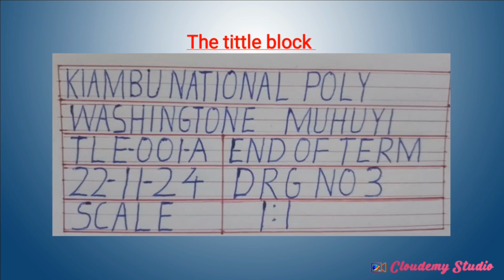So after understanding the types of lines, now we'll move to the next part, which is the title block. I'll really emphasize the title block since I told you that the marking will be done as a block. So at least an examiner has to see that you underwent a class of engineering drawing and you are taught how to design a good title block. So for this, I've just designed a sample of a title block where I've included the name of the institution, that is Kiambu National Poly, the name of the student, your admission number, then I have written end of term, then the date, then the drawing number 3.